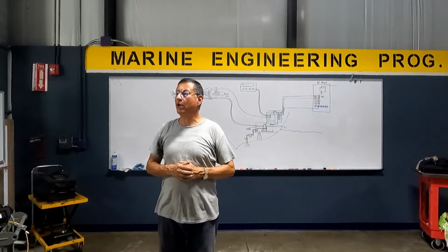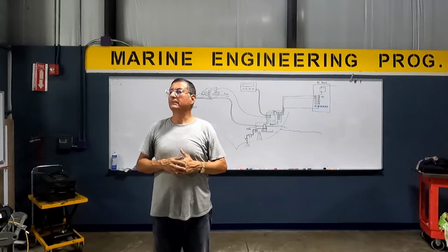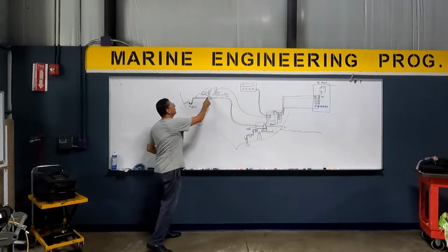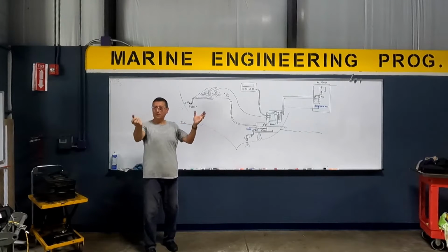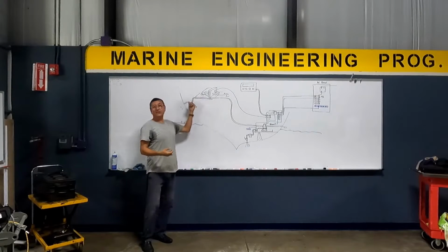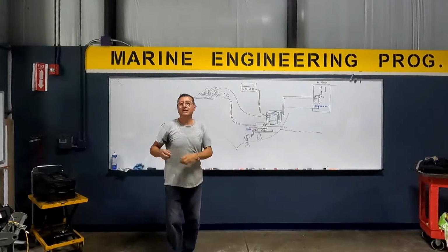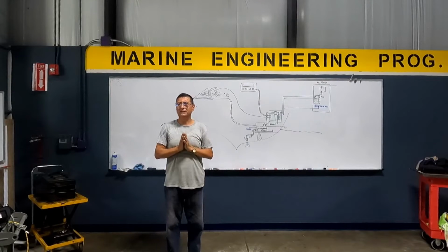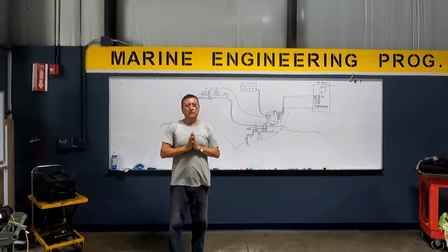Where is located the condenser coil? Outside. Where is located the evaporator coil? Inside. What is the function of the evaporator coil? To freeze and cool the ambient air. Absorb heat from the ambient air, reduce the temperature. That's the function. No? What is the function of the condenser coil? Release heat. Is it clear or not, guys? Yeah? Good?